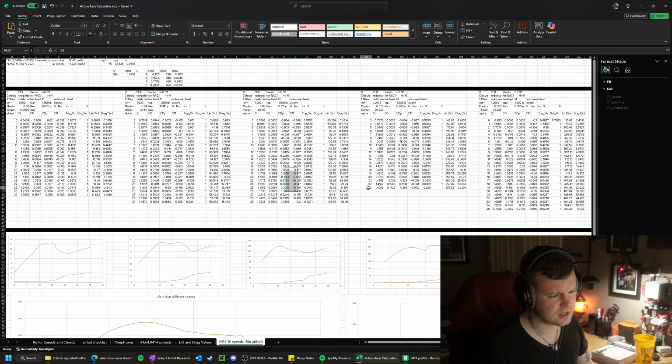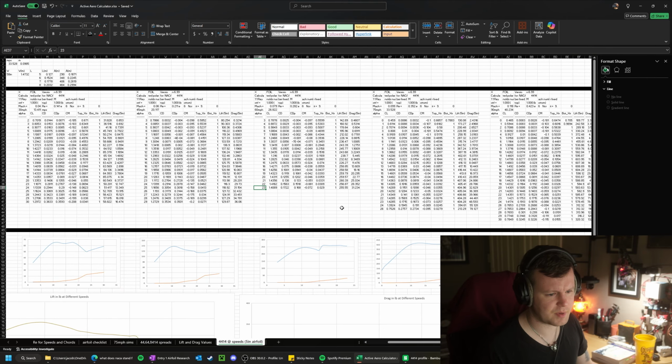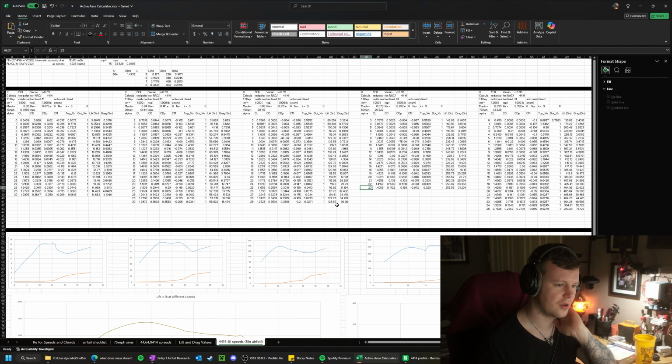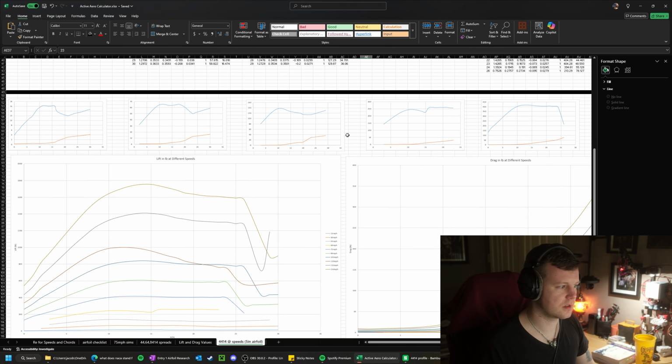Some of the simulations cut off around 23 degrees, but I think we start to get boundary layer separation around there anyway, so I wasn't really concerned about that. I don't think we're going to angle the airfoil much past 20 degrees, unless we're in a braking scenario, and then, you know, that's a different transient that we have to think about.